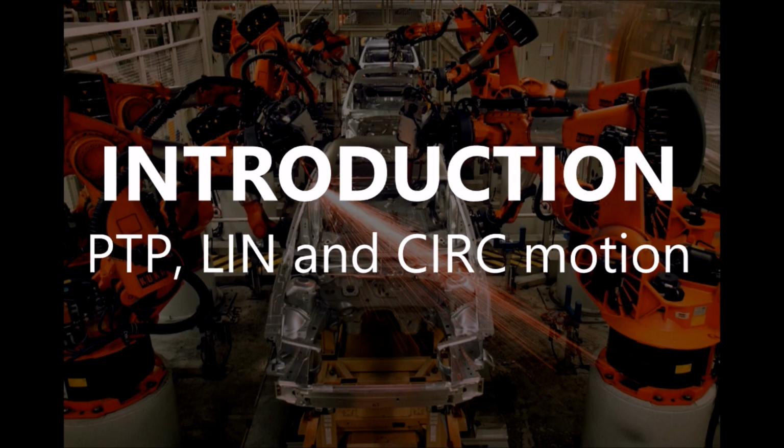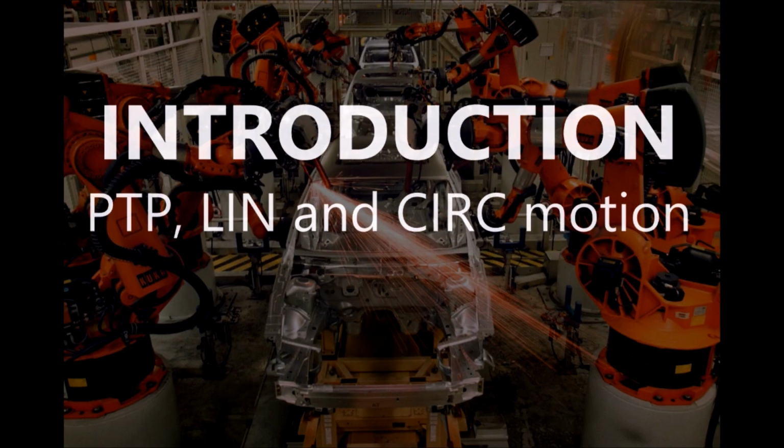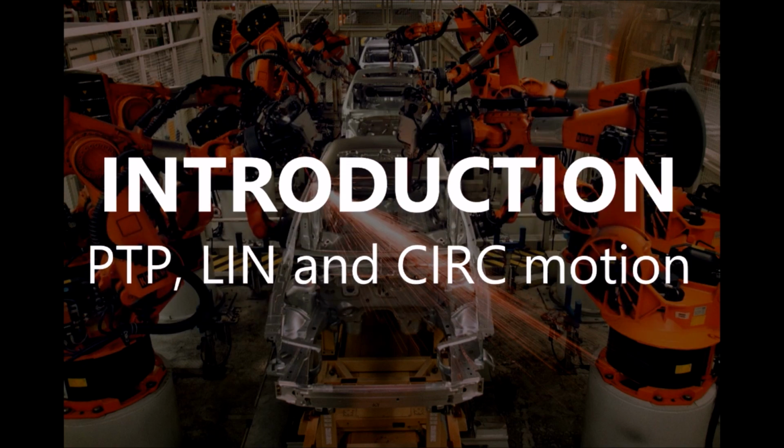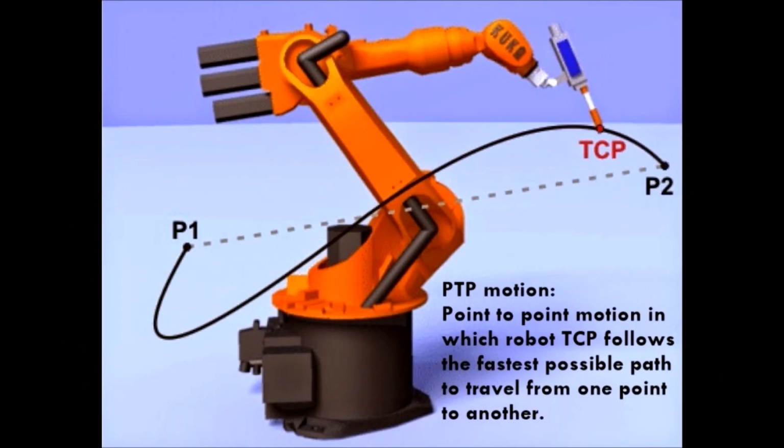Hi, I am going to introduce three types of KUKA robot motions, which are PTP, linear, and circular. What is point-to-point? The PTP motion. When PTP motion is applied for the path from P1 to P2, the tool center point, the TCP, will follow the fastest possible path instead of the shortest path. Based on the figure, yes, the solid line instead of the dotted line.